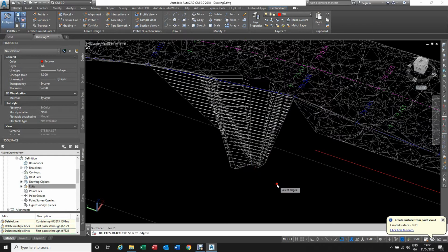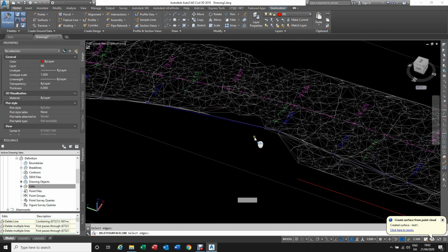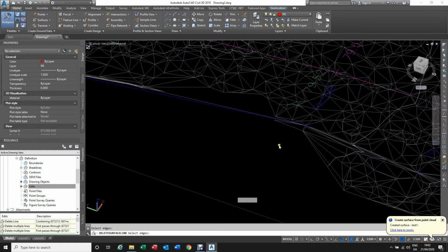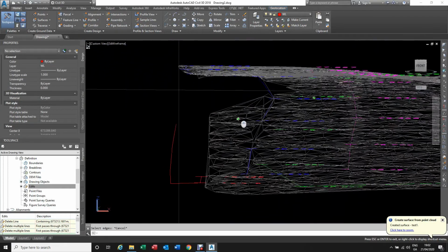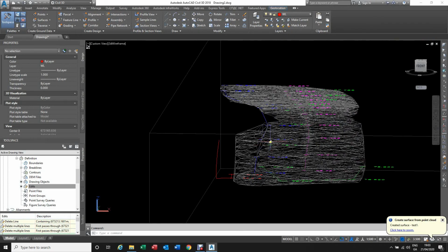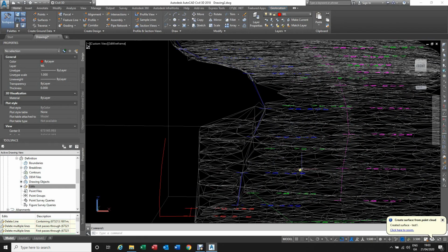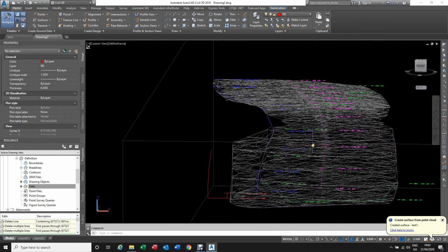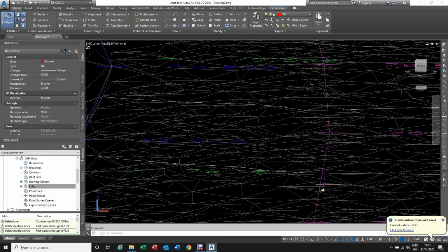Delete surface line. Helped a little bit, yeah. Yes, and you see, because we made part of the surface, how we created with this one these long triangles, which are not very good, to be honest. So once we have a really fine surface we can project like here the line to the surface.